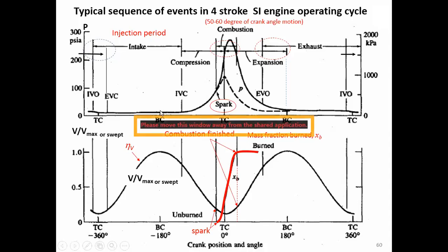Right. The piston starts moving up until it moves away from the bottom dead center a little bit. The inlet valve closes, and that means it is the end of the intake stroke. So the intake stroke happens on both the piston moving down and moving up. This is what happens in the actual cycle.